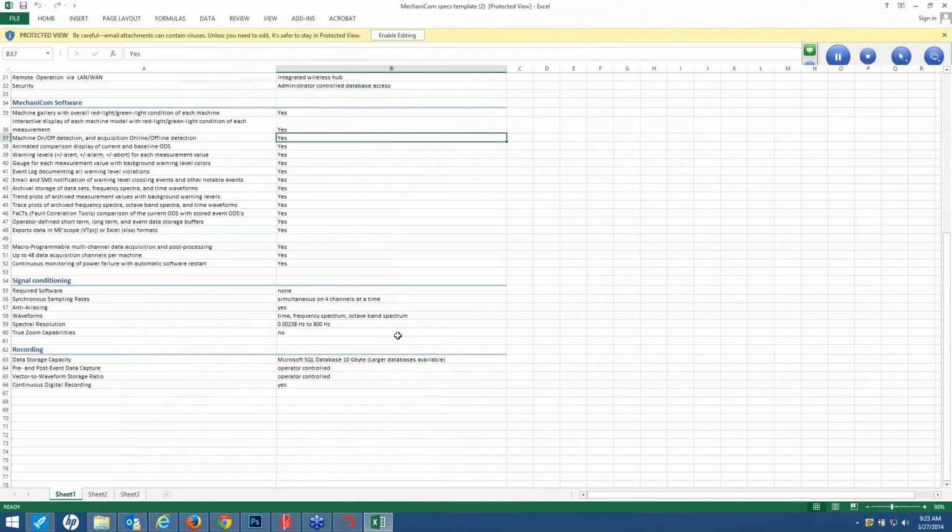But I guess that begs the question: if I just go and buy a bunch of this hardware and software and set it all up on a brand new machine that we've never seen before, are there any rules that say, okay, lots of vibration at 1 times is unbalance, 2 times in the axial direction is angular misalignment, lots of multiples of rotation speed means something's loose? Are there rules built into the database that will let it look for faults on the get-go?